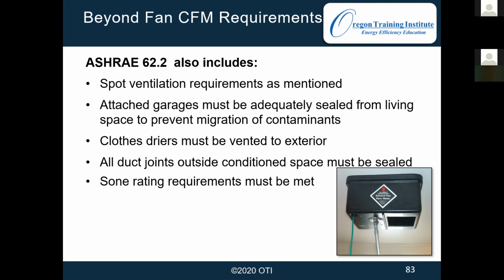New fans that we install have to meet the loudness requirement and the zone requirement. So continuous run fans, that means no more than one zone, while intermittent fans can be up to 3 zones. And those are new fans, not existing. This doesn't apply to existing fans.